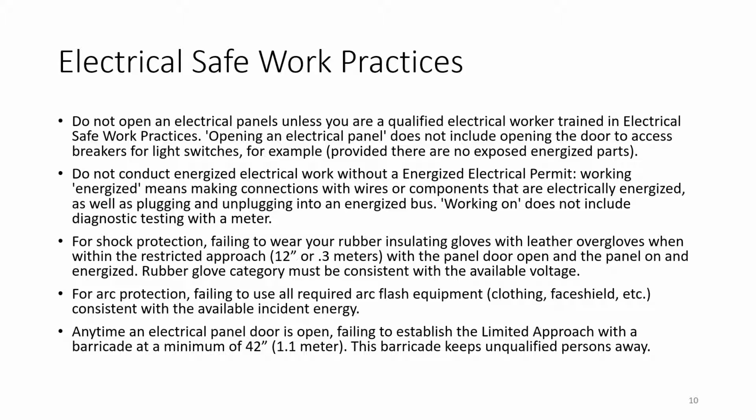Working energized means making connections with wires or components that are electrically energized, as well as plugging and unplugging into an energized bus. Working on does not include diagnostic testing with a meter. For shock protection, do not fail to wear your rubber insulating gloves with leather overgloves within the restricted approach area of 12 inches or 0.3 meters, with the panel door open and the panel on and energized. Rubber glove category must be consistent with the available voltage.